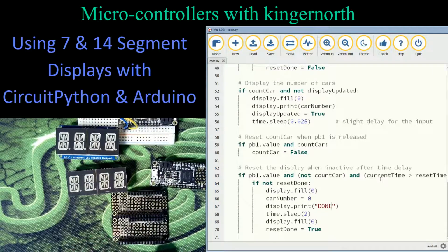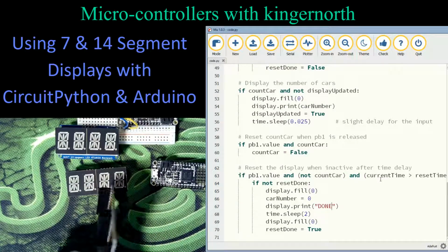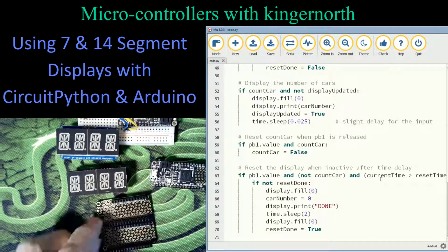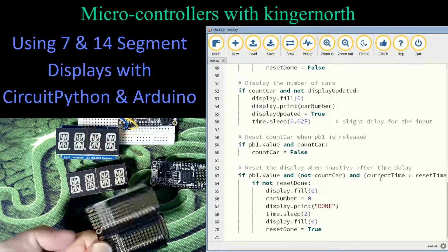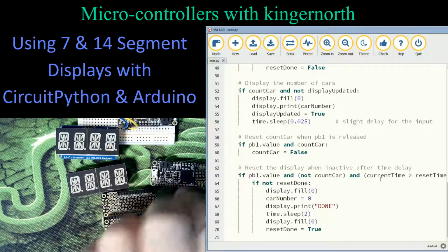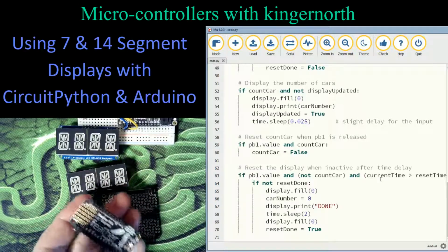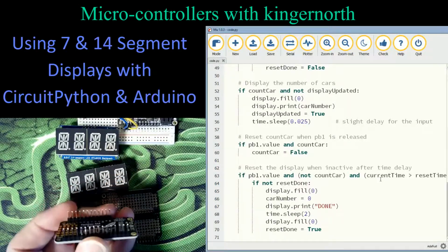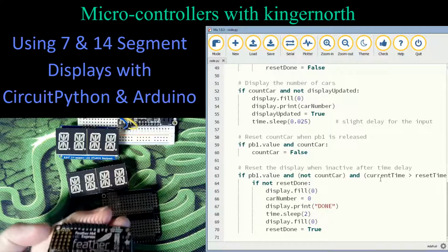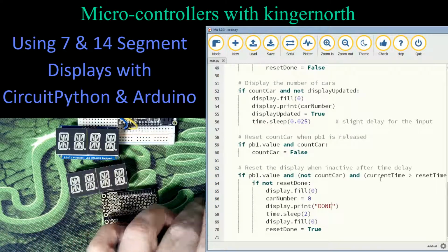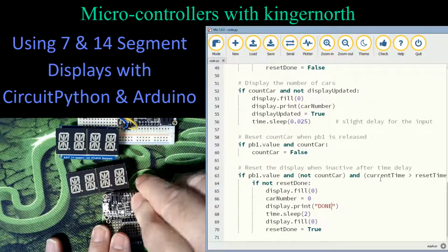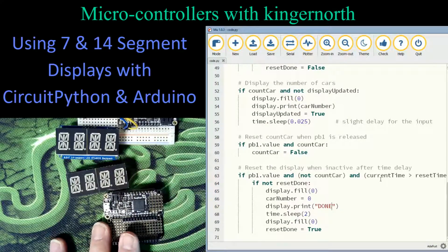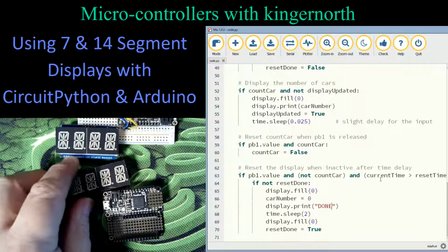What I have here is a board that's already pre-wired. All I had to do was solder the headers onto it. When you buy them, you just get the printed circuit board and the headers. And these are in the pattern of the pins on the bottom of this feather format. Feather format is a unique format that's a standard. So that allows me to take it, plug it in on this board, and it allows me to use it instead of a breadboard.